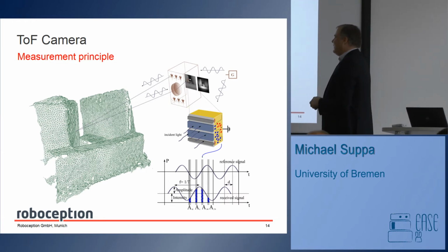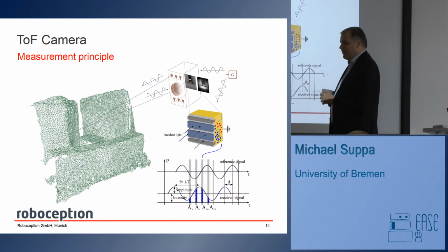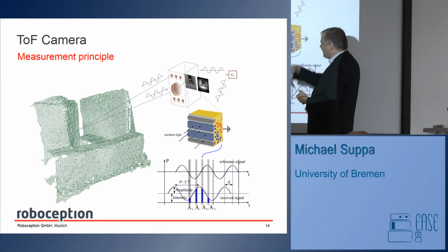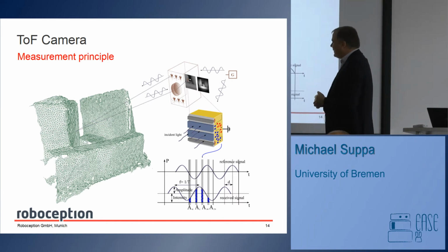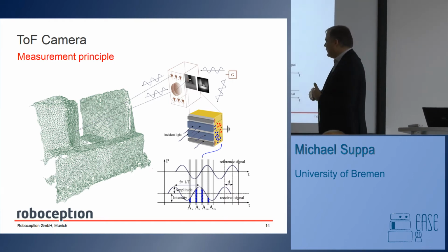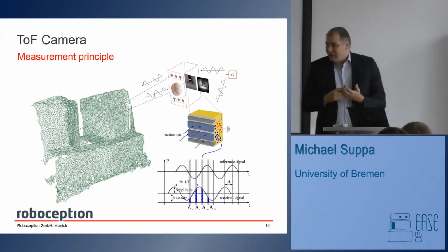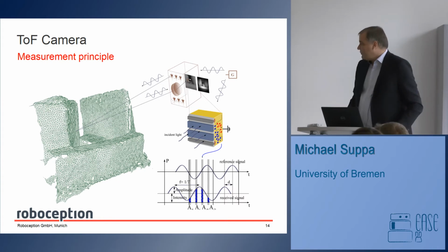in doing this, you can later on determine the distance the object is away. As it is an active system, of course, it's interfered with by the ambient light. So you have to make sure that the light you're getting back is really from your active transmitter. There are a couple of ways you can do this, but still sunlight is in many cases a big issue here, especially for that kind of principle. That's also why some of these systems don't work outside.